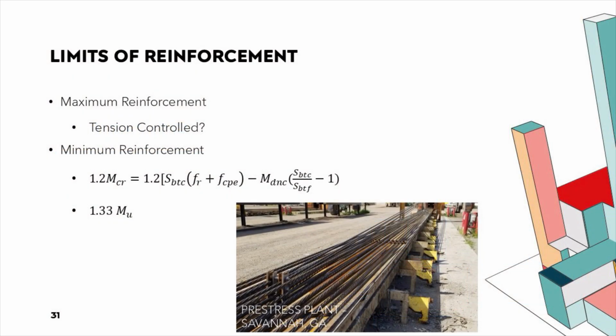If a beam is over-reinforced, it causes the ductility of the beam to decrease, which in turn will reduce the allowable deformation of the beam. If the beam is tension controlled, then we can assume that the beam is not over-reinforced. At any section of the beam, the amount of pre-stressed and non-pre-stressed tensile reinforcement must be adequate to develop a factored flexural resistance equal to the lesser of the equations provided. Since we know the maximum moment is at the midspan of the beam, we use that to determine if the minimum reinforcement requirement is met.